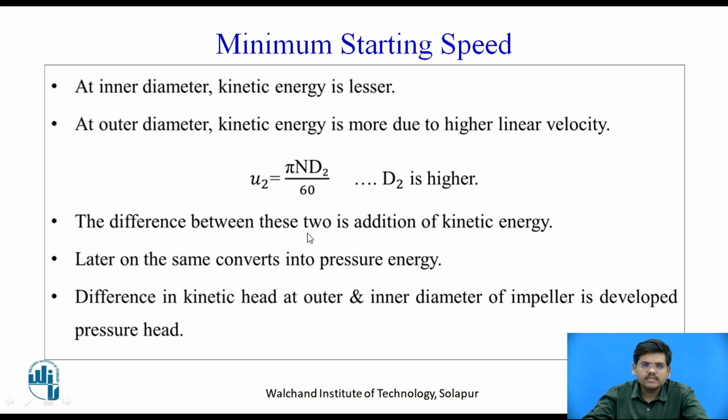Now the difference between these two kinetic energies is the addition of kinetic energy. This difference helps to add kinetic energy to the fluid, that is, the building of pressure. Later on, the same converts into pressure energy. The difference in the kinetic energies causes the addition of kinetic energy to the fluid, and that same kinetic energy is converted into pressure energy. So the difference in kinetic head at outer and inner diameter of the impeller is nothing but the developed pressure head.